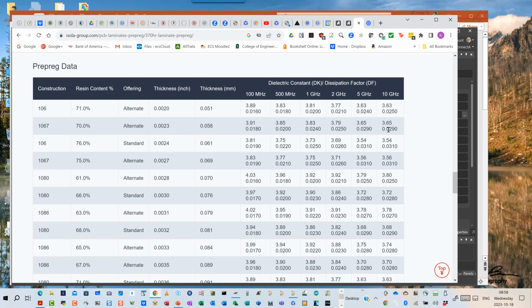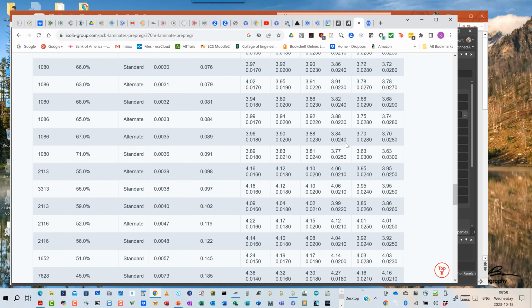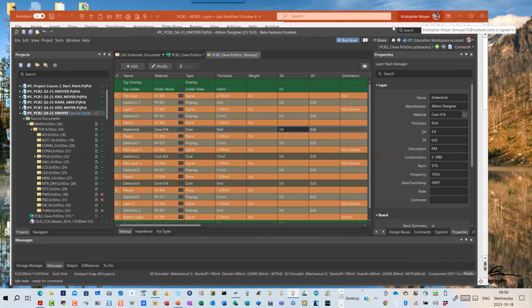So I'm going to use 3.9 as my number here. The bulk of the thicknesses I'm choosing, the 4 and 5 mil layers right there, are going to come in here in that 3.9 type of range. So that's where I'm getting these from, right here from the manufacturer. And most of the major manufacturers out there, Isola, Arlon, Nelco, and so on, provide that kind of data. You don't even usually have to call them. It's usually right there on their web page for the sheet. Does that answer your question?